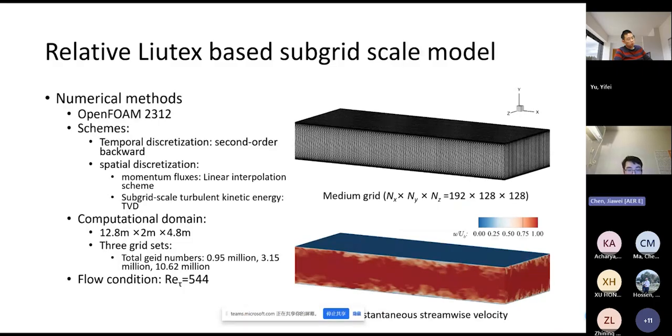In this slide, let me describe our numerical implementation. We are using OpenFOAM with second-order backward temporal discretization and linear interpolation for momentum fluxes. And for the subgrid scale turbulent kinetic energy, we use TVD schemes. And for the computational domain, our computational domain is